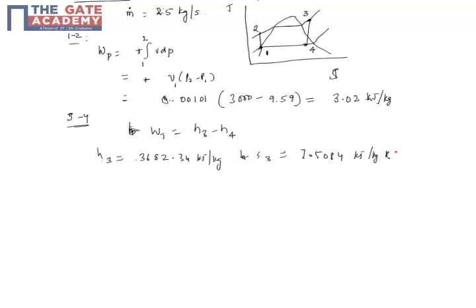Remember, we have to decide the dryness fraction at 4, because only then can we get H4, which we don't know. First we use the property of the reversible adiabatic process, that S3 is equal to S4, and S4 can be written as Sf at 9.59 kPa plus dryness fraction times Sfg, which is how you write the properties of wet steam, also at 9.59 kPa.